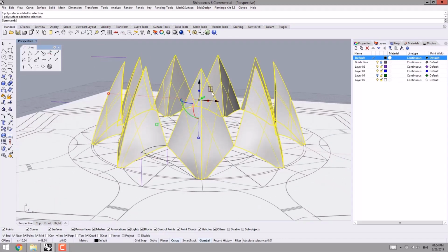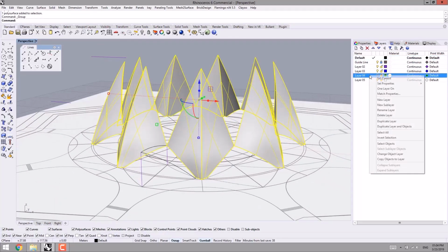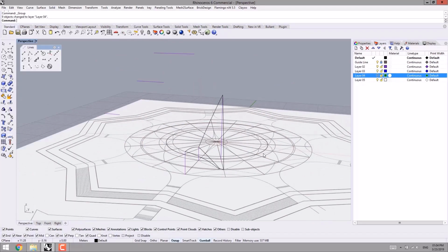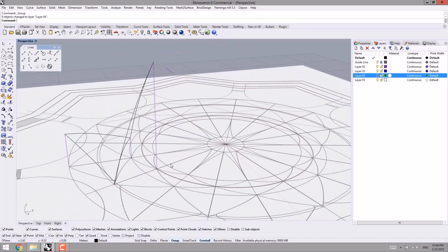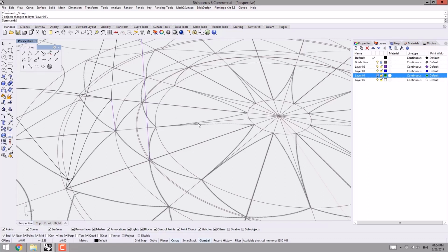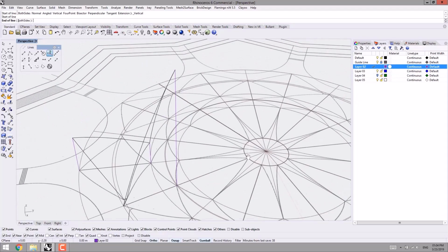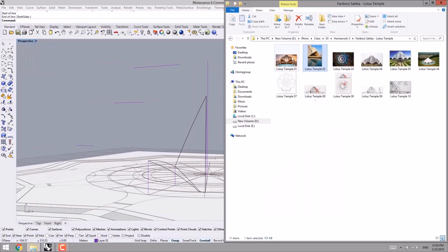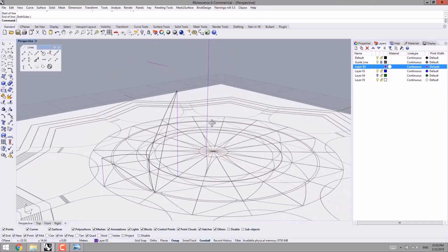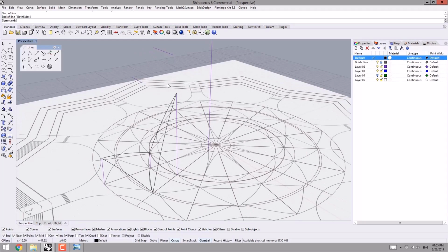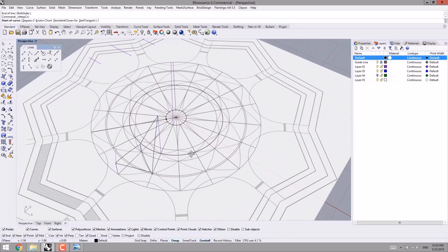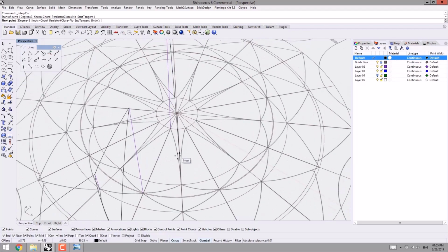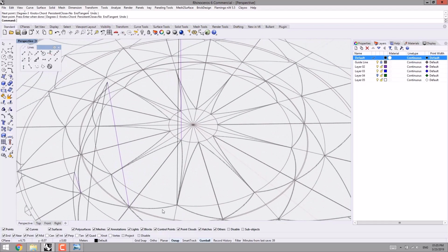Then I select all of the surfaces to group them, Ctrl G, and then I set them to layer 4 actually, by this way. And then for the last stage, we're gonna move it forward by using a vertical line. At layer 2, I extend it till the 3rd elevation. Well done. And then the next curves by using interpolate curve and then creating the surface from this point to